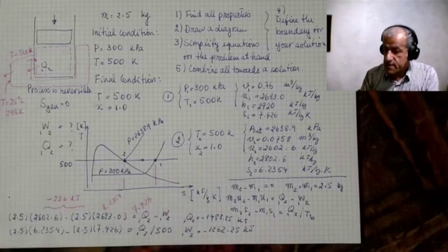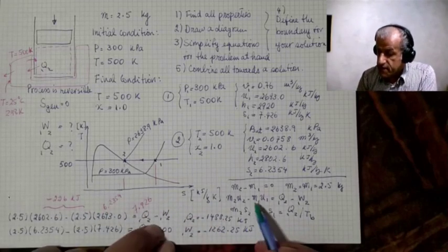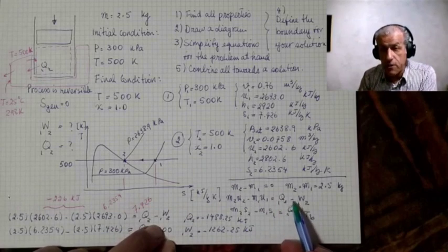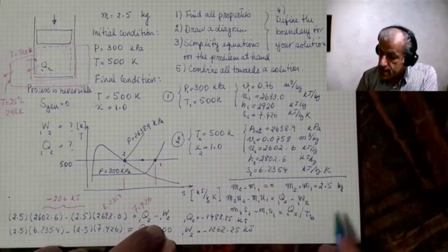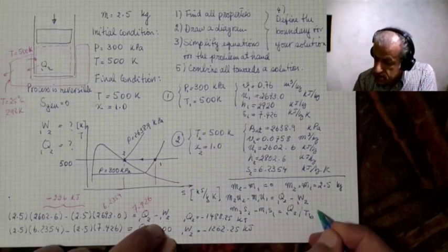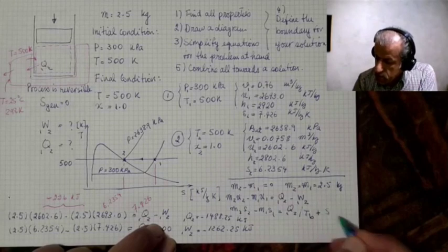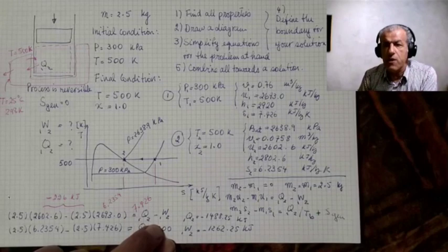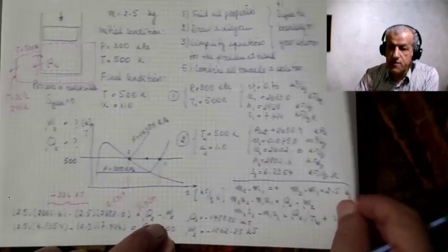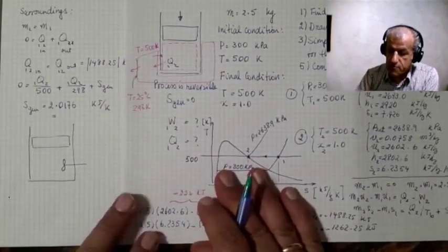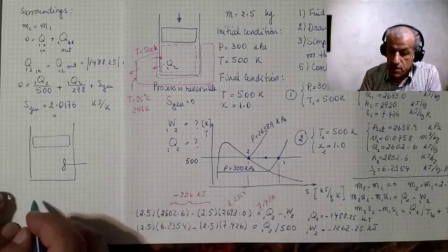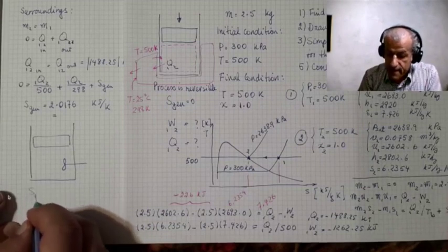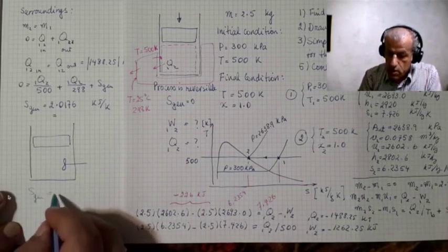If that is the case, then the first law of thermodynamics would remain the same, although the numbers for Q and W would change. And the second law of thermodynamics would be the same, except that there would be an S gen added to this term. Because why? Because of the propeller, which is producing this S gen. So now we have an S gen which equals